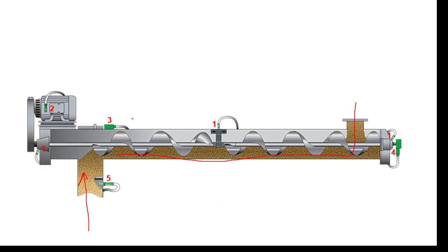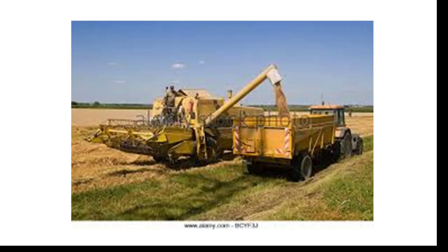It is a conveyor. If the inclination angle of such a mechanism, where the main part is an Archimedes screw, is horizontal or near to horizontal, then it is called a conveyor. It conveys the particles from here to there. But if the inclination is not horizontal, but in the order of an acute angle or right angle, then it is mainly called an elevator. Especially if the part where we have an Archimedes screw is vertically oriented, it is called an elevator, Archimedes elevator.